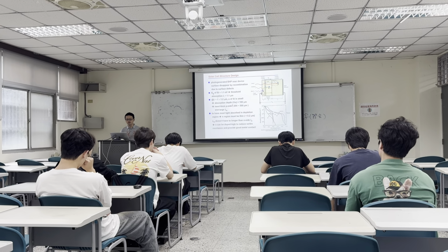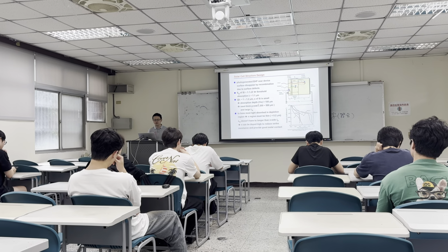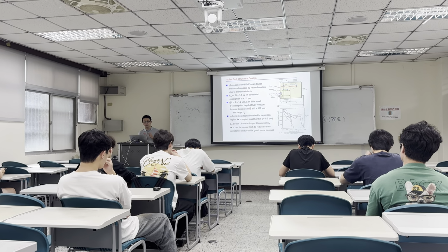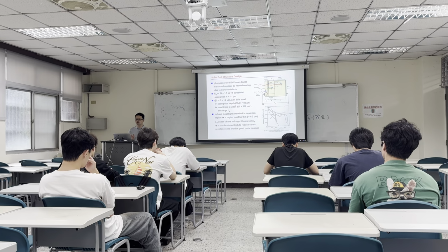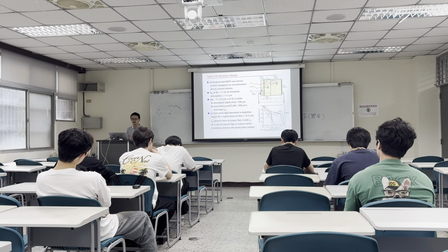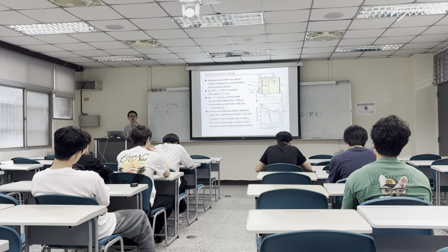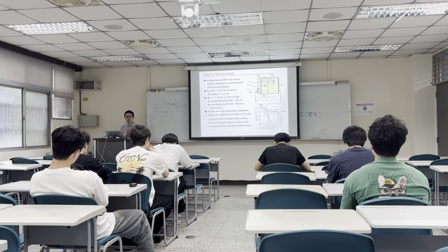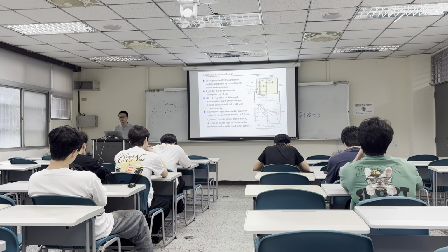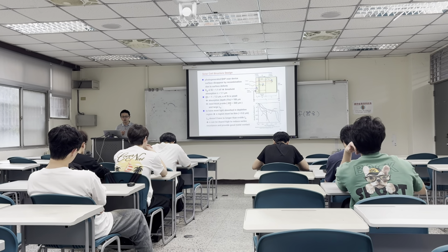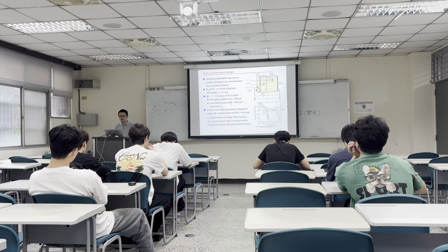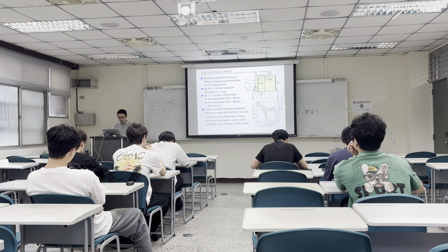You're going to need a very thick P region, usually a thickness of about 200 to 500 micrometers. But we're not going to make this solar cell that thick, because with a very thick P region, you're going to increase the series resistance. That's detrimental to the output performance. So usually the thickness is about 200 micrometers. So for the longer photons within this range, there's no contribution to the output power.